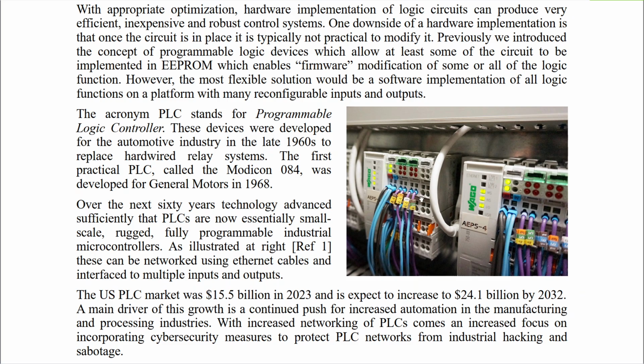So, for example, here we have PLCs mounted on a rack. There's a power supply over on the left here. And then your CPUs are here in this block. And then you have various input and output sections that can be mounted. And the nice thing about this modular structure is that if you need more inputs or outputs, you can just put more of these I/O blocks on there.